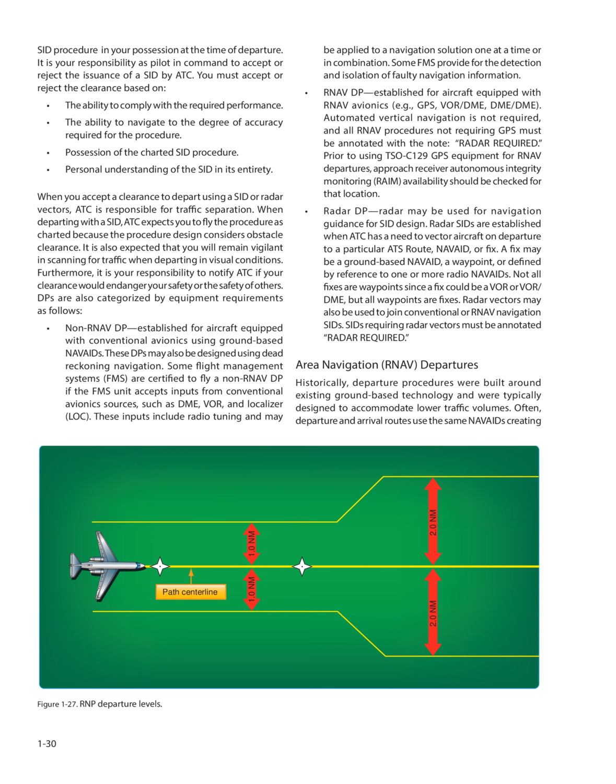You must accept or reject the clearance based on the ability to comply with the required performance, the ability to navigate to the degree of accuracy required for the procedure, possession of the charted SID procedure, and personal understanding of the SID in its entirety. When you accept a clearance to depart using a SID or radar vectors, ATC is responsible